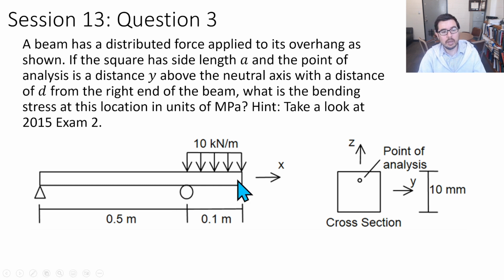Another thing that's a little bit different is we're not going to do our query at the top surface or at the neutral axis, where it's just 0. We're going to do it at some location here. It's not super common, because usually you're concerned about the maximum stress, so you go to the outskirts. But we're saying that we can calculate the bending stress wherever we want in a beam with a pretty standard cross section.